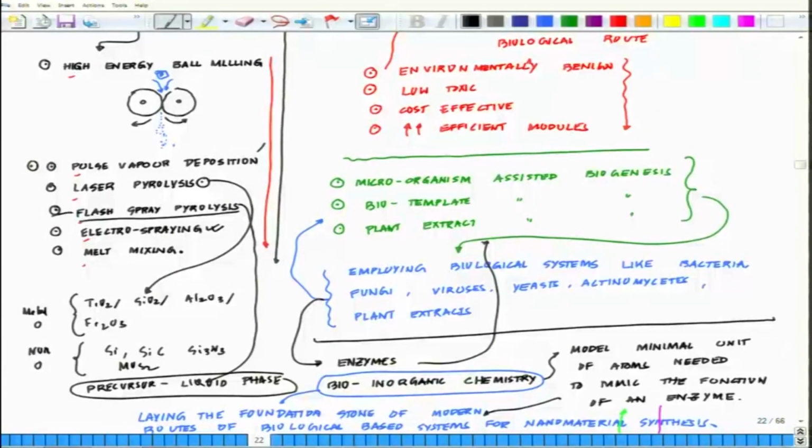The solvent is evaporated on its way to the counter electrode and particles or fibers are then collected at the end. The electrospraying technique provides both flexibility and control of the surface parameters, and electrospraying is one pretty neat process to produce nanoparticles.